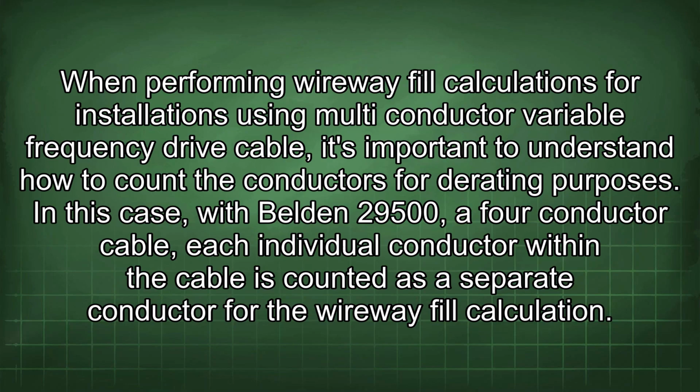When performing Wireway fill calculations for installations using multi-conductor variable frequency drive cable, it's important to understand how to count the conductors for derating purposes. In this case, with Belden 29500, a 4-conductor cable, each individual conductor within the cable is counted as a separate conductor for the Wireway fill